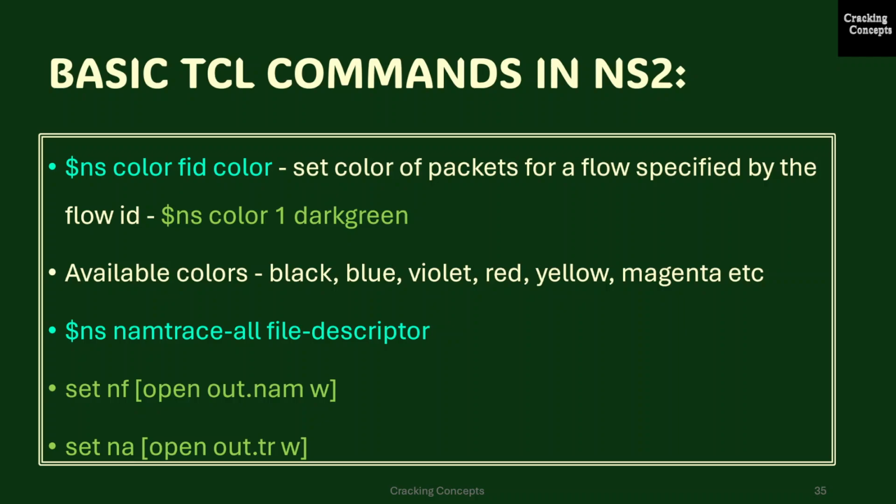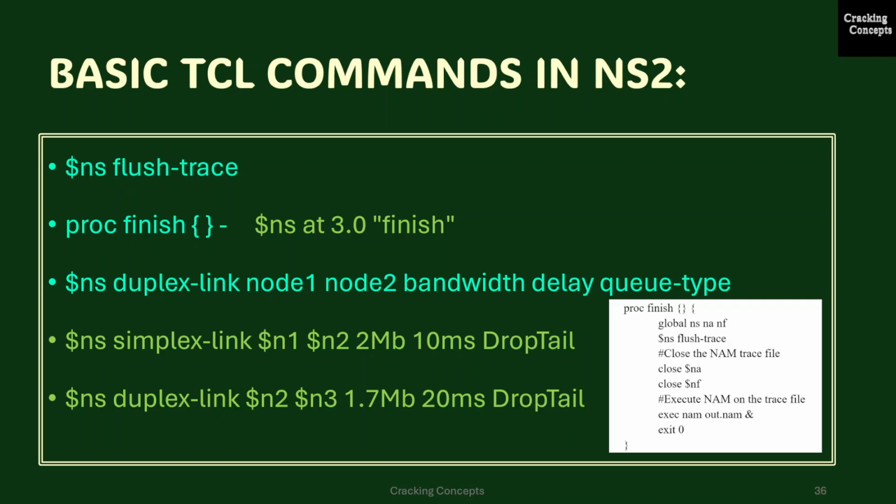Within the TCL script, these files are not called explicitly by their names but instead by pointers that are declared as nf and nd respectively. This member function tells the simulator to record simulation traces in NAM input format. It also gives the file name that the trace will be written to later by the command $ns flush-trace. Similarly, the member function trace-all has a parameter, the name of the file where the traces will go. With this simulator command, we trace all the events in a specific format.